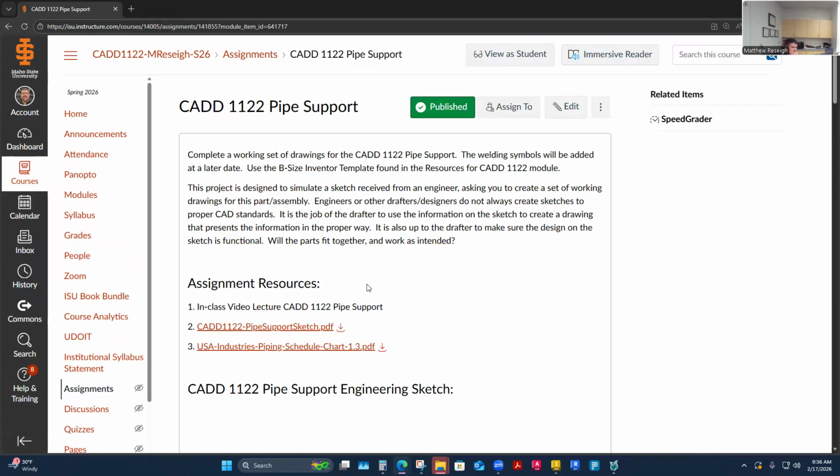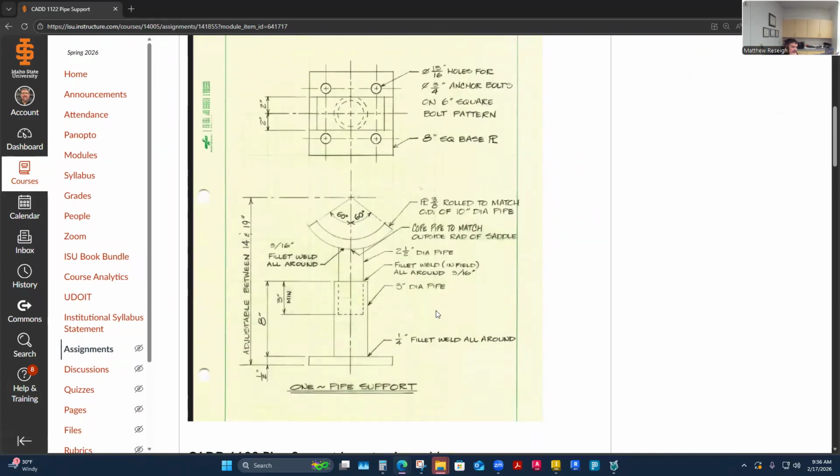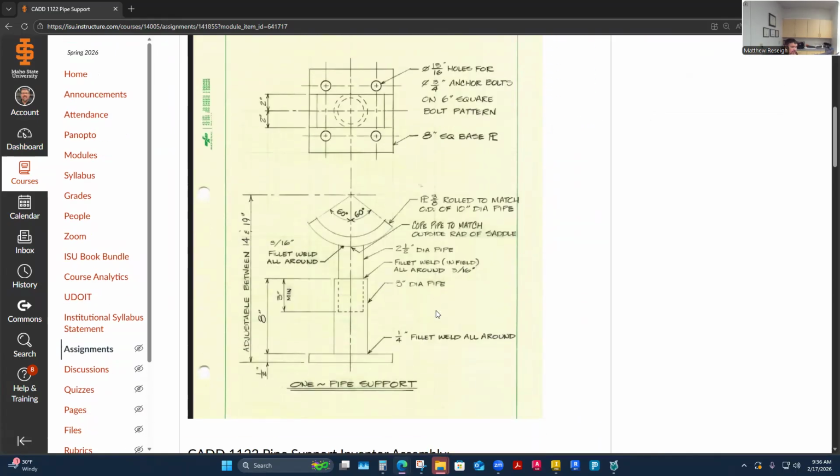Let's see here. I'm kind of building it in the relationship they're going to be to each other once they hit an assembly. And it's going to make the assembly really fast, but I don't always do this with all parts, but I think from the end here of my part, I'm just going to offset a plane 3 inches from there. And I'm going to build this thing kind of from there down.